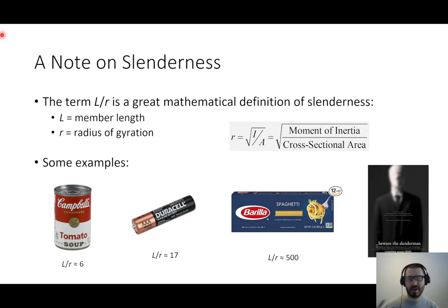If you've had me for Engineering 216, one of the examples I use is if you've got 2x12s and you're standing those up as floor joists for, let's say, a roof deck or your back porch, those beams are going to be oriented like this, not like this, because when you bend a 2x12, it's just stiffer one way than it is on the weak side. That's because the moment of inertia is larger along that axis than along its weak axis.